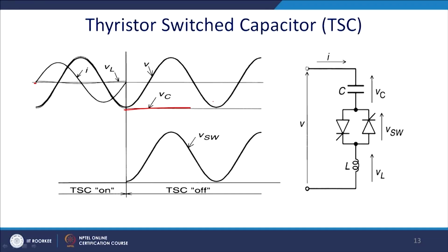So, the capacitor will maintain this voltage, and thus the switch will be subjected to this oscillation and will have a stress of this voltage value equal to V, if the value of n, which is quite logical, is very high. So, n square minus 1 is almost equal to n.